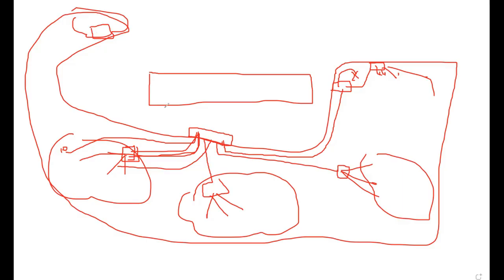In the main distribution boards, you can see the air circuit breakers, which I showed before, and apart from that, MCBs. But in all of these, you can see only MCBs and MCCBs. That's it. No other things will be there in all these distribution boards.